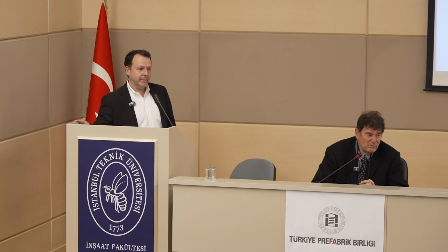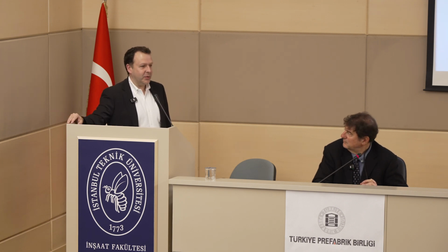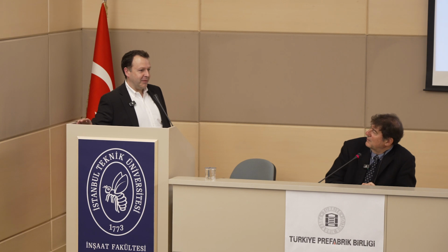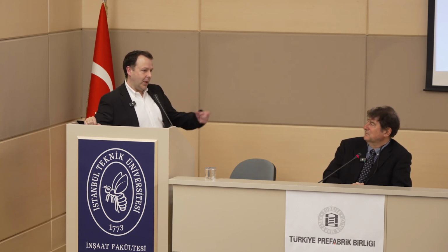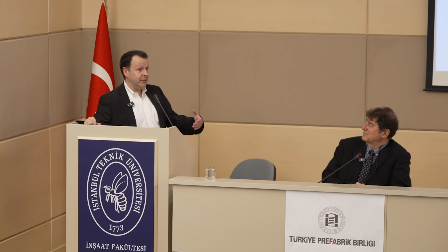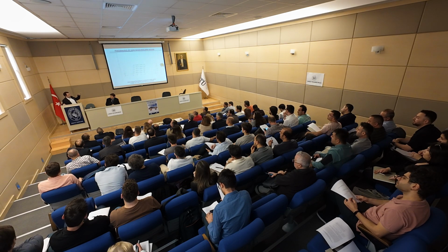Plastic hinge wasn't put only at the base of the column, it was put in the upper floors, but didn't go to plastic hinge. In this model, and in the interest of time of having these results, the columns are modeled with 0.7 EI, but the hinges were not assigned in this model.